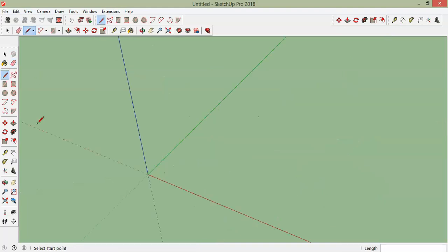Sometimes when you want to use line command, first erase this. Click line tool, make a square, follow the green line, then red line. Then you will want to close it while aligning the starting point. For that case, you will need to hold Shift key, then click the starting edge. Now release the key. From here you can add other geometries or simply close it. So for aligning such objects, you can use Shift key shortcut.